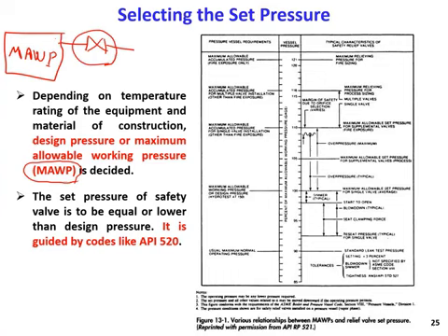I will design it based on the maximum working pressure, as well as how much temperature this reactor can tolerate, and what the material of construction is, whether steel, iron, whatever. Those are also important in selecting the valve.